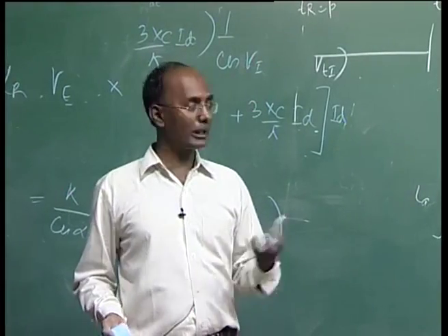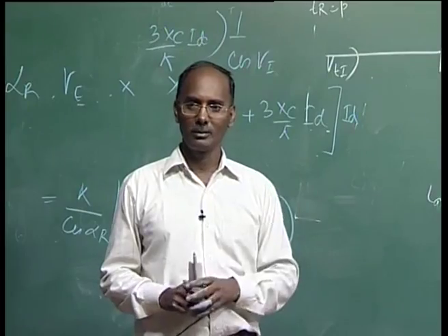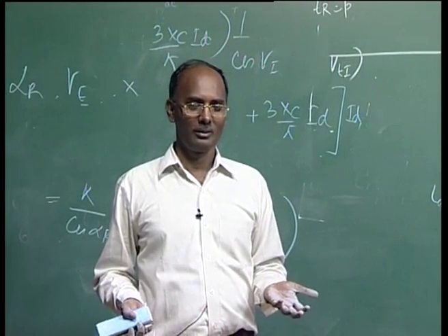Now, the question is, if this Jacobian is not modified, how is HVDC going to be taken care of? If there is no change, it is only AC load flow, so where is the DC now?